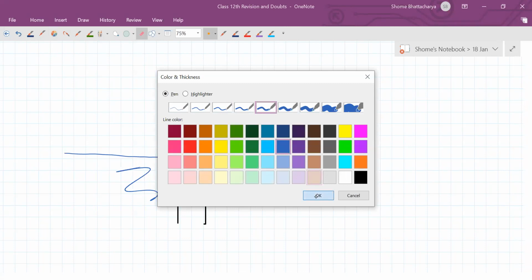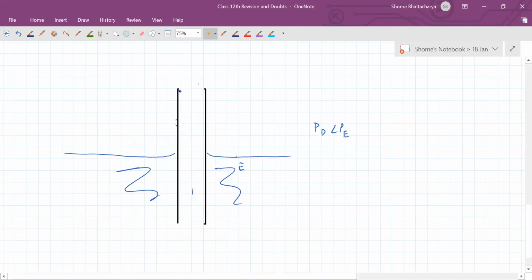Even if this meniscus were of that natural angle 53, the pressure at this point just inside, let's say B, is lower than atmospheric pressure by such a large amount that rho g h is not able to compensate. So this thing is just not happening.